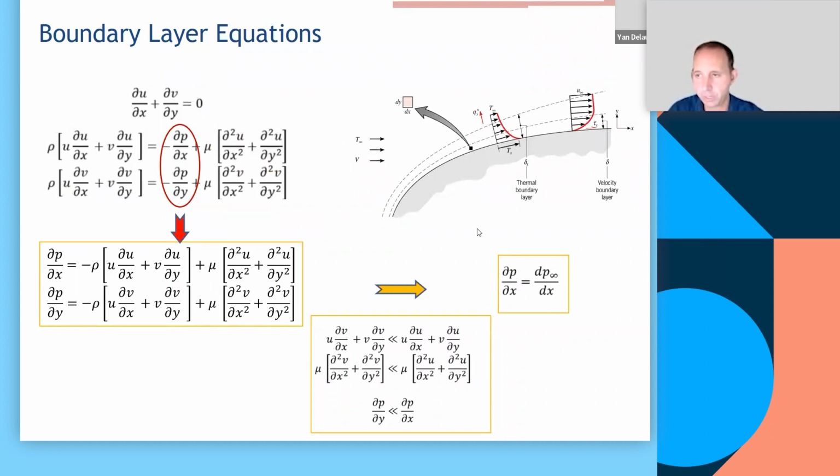We go back to a sketch of our boundary layer flow, and we consider the two equations side by side. So let's look at the pressure term. What does create a pressure gradient, by the way? If you have a flat surface, completely flat, rather than this curved surface, we know that's called an external flow over a flat surface, and we know it will create no pressure gradient, and that can be proven. I won't discuss it too much, but what we know is that outside of the boundary layer, the pressure here is going to be the same as what you find anywhere along the y direction.